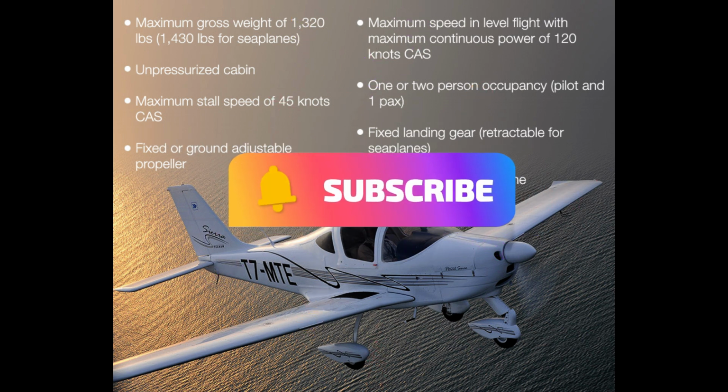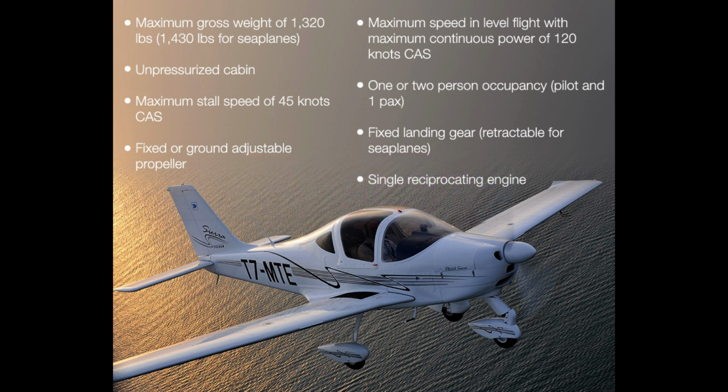Airworthiness certificates are classified as either standard or special. Standard airworthiness certificates are white and are issued for normal, utility, acrobatic, commuter, or transport category aircraft. They are also issued for manned free balloons and aircraft designated as special class. Special airworthiness certificates are pink and are issued for primary, restricted, and limited category aircraft and light sport aircraft. They are also issued as provisional airworthiness certificates, special flight permits, ferry permits, and for experimental aircraft.